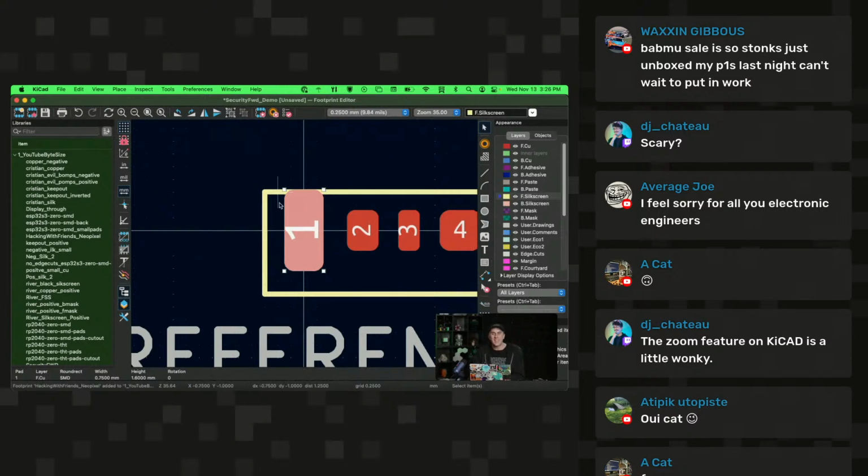And I also need to make a keep out region to make sure that no other components or no silk screen gets placed here. But yeah, so aside from that, this is mostly where I want it to be. And that was the hardest part for me.